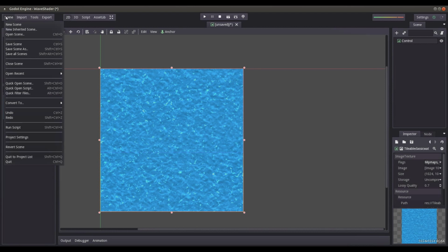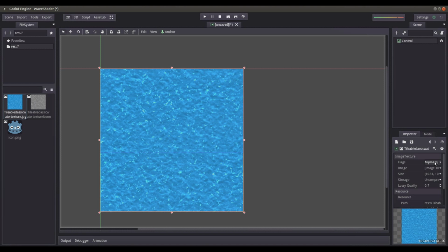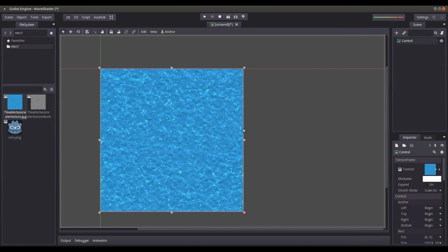And so how you set it in the project is you go over here, project settings, image loader, and check repeat on. I think that might be a small bug because it doesn't recognize it from the shader. If you don't, you'll make it on the object itself, set this repeat button, and when it plays in the player, it doesn't actually repeat. It just kind of gets stuck. So that's one thing that you have to remember to do, in the project settings, set that image to repeat. Otherwise, it doesn't work at all. So that's all we have to do to get the project ready.